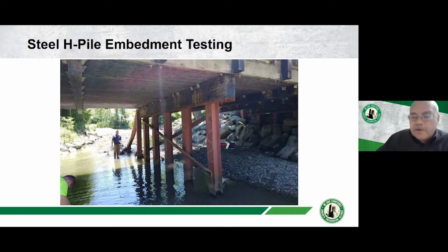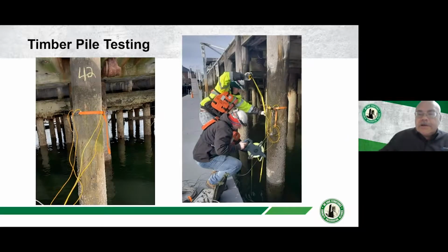So these were end-bearing piles, very safe to excavate down in the gravel into the riverbed, a couple of 2-3 feet, do the repairs on the perforated steel in the splash zone, and the load posting was removed from this particular locally owned bridge.